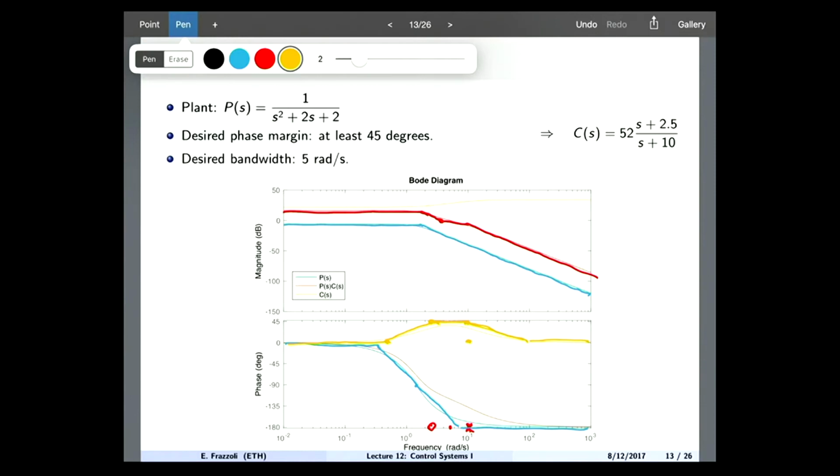But if you want to get precise, then you will go to MATLAB, and MATLAB will allow you to figure out exactly what is the exact spacing between the pole and zero. But the point is, I choose 5 to be the geometric mean, multiply by 2, divide by 2, and I get the pole and zero locations. Or multiply by 5, divide by 5. Typically, when you want to overdo things, separate well and get almost 90 degrees of phase margin, you multiply by 10 and divide by 10, and you don't go wrong with that. If you want to be a little bit more precise, you can reduce those multipliers. Clear?